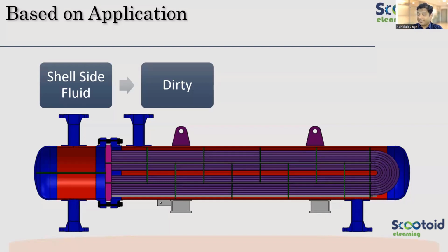So are you saying that it will be difficult to clean? Okay, the next question. The complete configuration with tie rods and baffles, we call the tube bundle. So can I remove that tube bundle? Can I access the tube bundle first of all in BEU type?